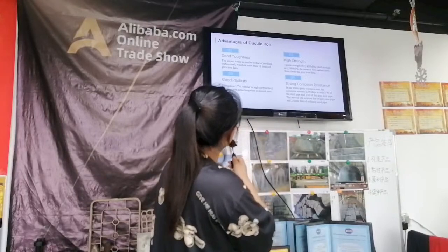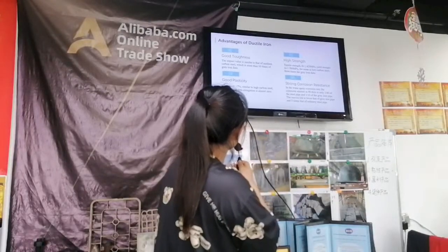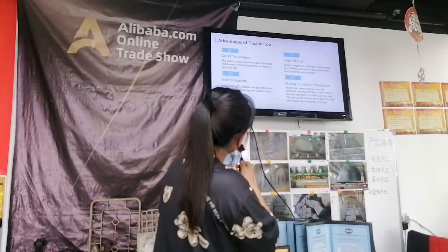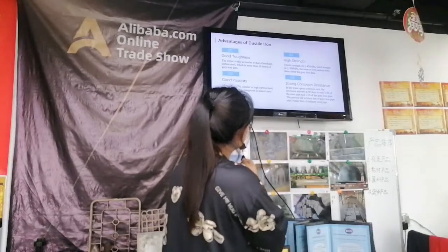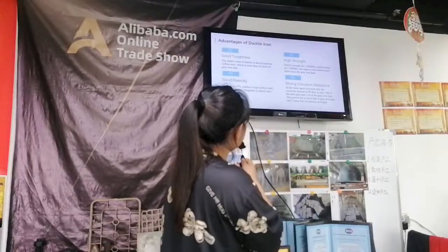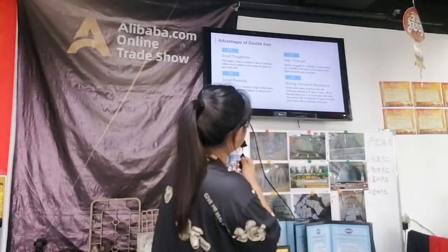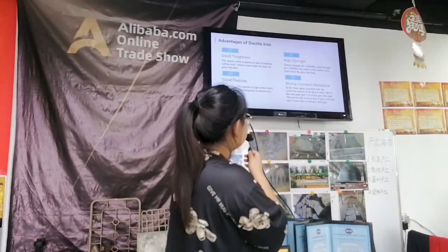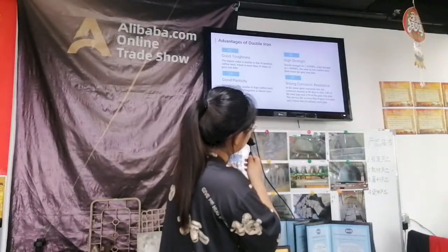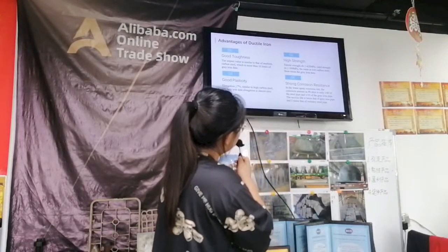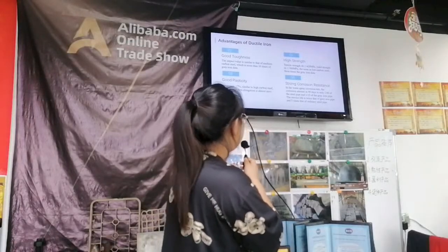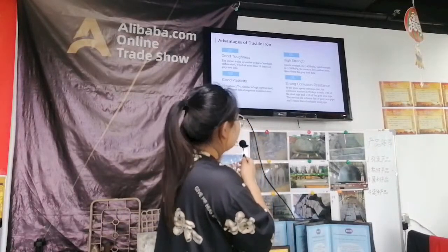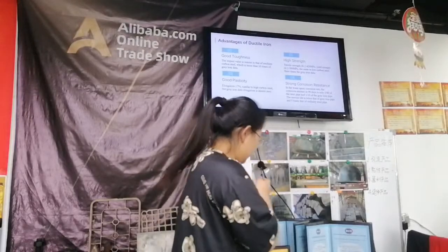And the third advantage of ductile iron is good plasticity. Elongation is equal to or more than 7%, similar to high carbon steel, but gray iron elongation is almost zero. The fourth advantage is strong corrosion resistance. In the water spray corrosion test, the corrosion amount in 90 days is only 1/30 of the steel pipe and 1/10 of the gray iron pipe. The service life is twice that of gray iron pipe and 5 times that of ordinary steel pipe.